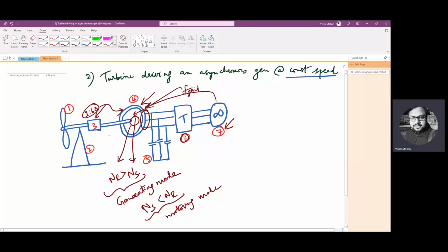For small variations in speed of the generator rotor, it won't affect the turbine, even though there is a load change or a change in the power imported to the grid. The rotor speed may be affected, but only a very low proportion of that is reflected on the turbine, because the ratio is 1:60, in this example. So essentially it's a constant speed turbine.